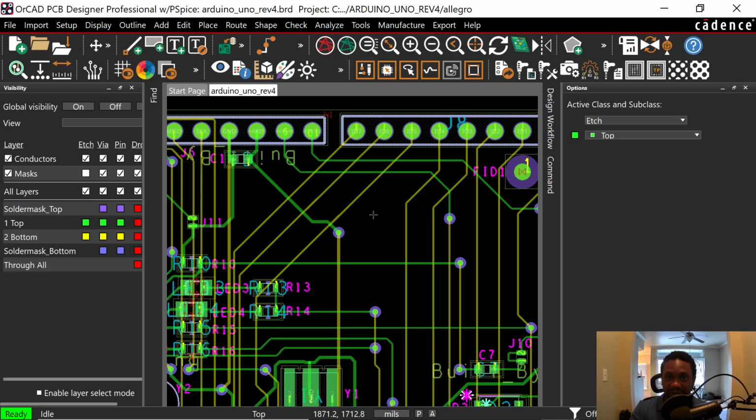Constraint Manager is the application. It's the tool that helps you apply those rules at all times in your PCB layout process. Once you play by those rules, whether they're electrical, physical, spatial, and whatever else, using Constraint Manager, you don't have to redo your work.